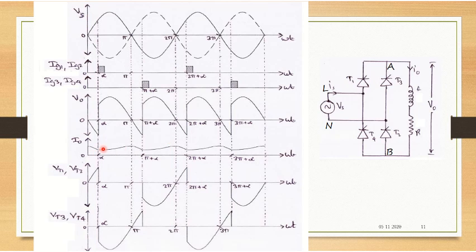If you observe, the current will be varying like this. When the output voltage is going negative, the current will be dropping, but because of T3 and T4 conducting again, the current will be rising. If you compare the current to the previous discussion with R load, in this duration the current was 0, but here you do have current at the positive potential.